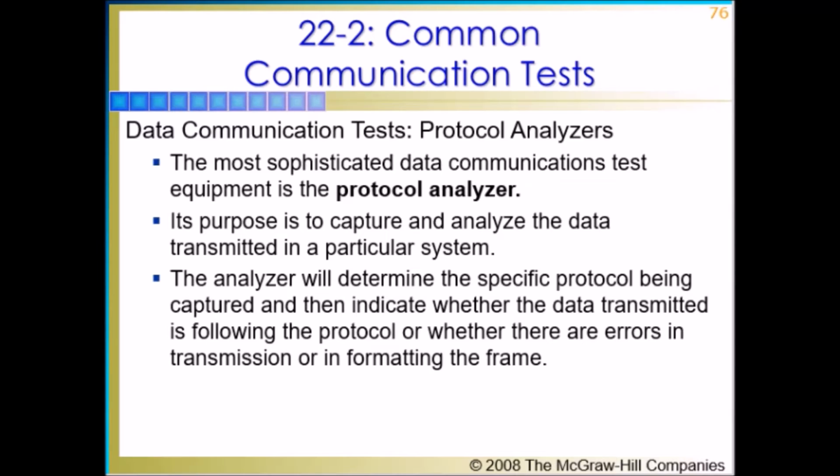A protocol analyzer can capture these frames, analyze them, and tell whether the system is operating properly. The analyzer will determine the specific protocol being captured and then indicate whether the data transmitted is following the protocol or whether there are errors in transmission or in formatting the frame.